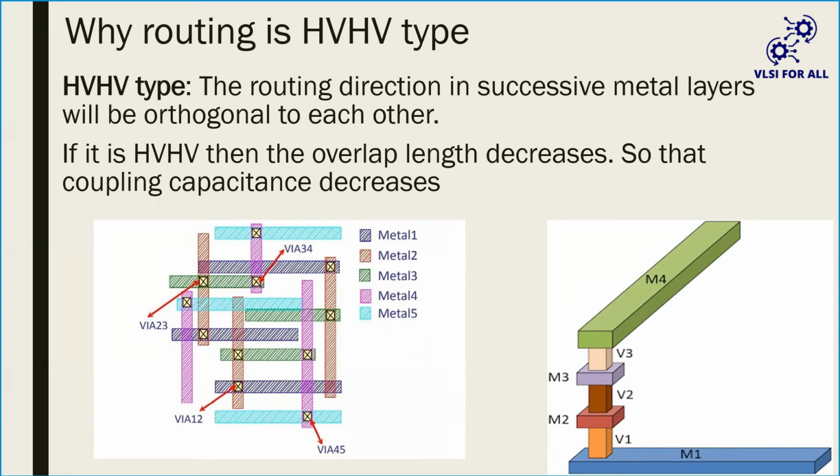Yes, team, you can see here metal layer 1, metal layer 2, the directions and all. See, there is a metal layer 1, in the right side figure, horizontal. Now, there is a metal layer 2, M2, that will be vertical, remember. And again, M3, horizontal. M4, vertical. So remember, if M1 is horizontal only, then M2 becomes vertical. In that way, horizontal, vertical, horizontal, vertical.